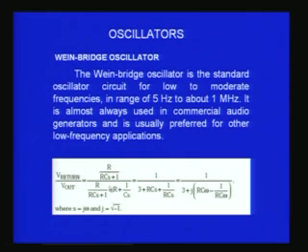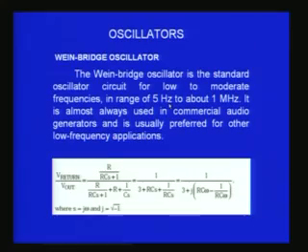One can also obtain the expression. I have given the expression, which you can test later, using 1 by RCS plus 1. This expression can be worked out on your own, and you would find it also leads to the corresponding gain being greater than 3 and the phase shift being 0. Now this RC Wien's bridge network can be used for generating frequencies in the range of nearly 5 Hz to 1 megahertz. This is the greatest advantage of the Wien's bridge oscillator built on the Wien's network.